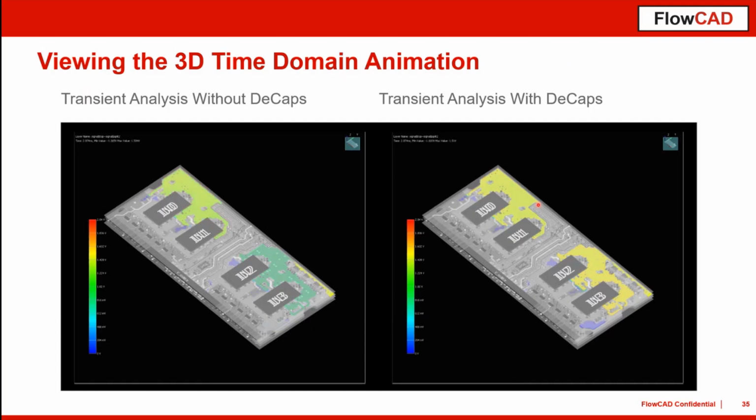That also helps to see where you may have to add some more decoupling capacitors to achieve a very smooth and noise-free power distribution network. This 3D visibility enables you to understand where you maybe have to place some more decaps to achieve this result.